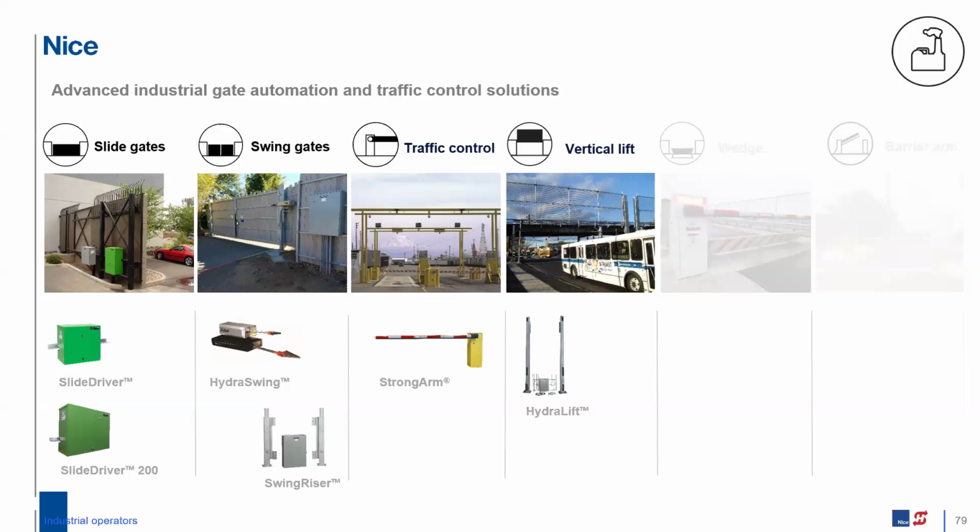This is going to be maybe where your site needs a little more security to it. So the gates could set flush with the grade, and when it goes to open, it'll lift up 4 inches. By the time it reaches full 90 degrees, it would be 12 inches above grade. So if you're trying to get around any curbs or anything like that, this is a great option.